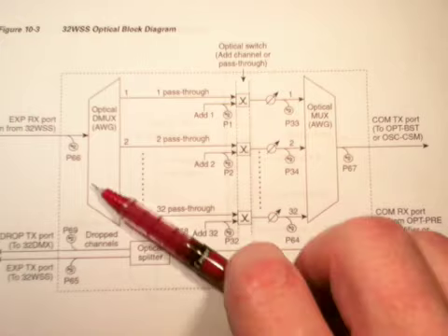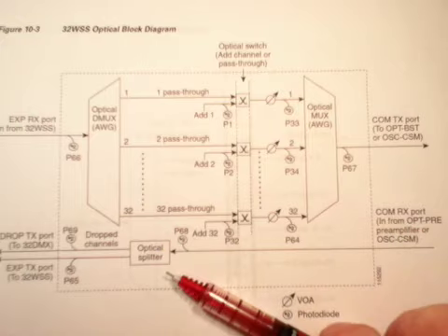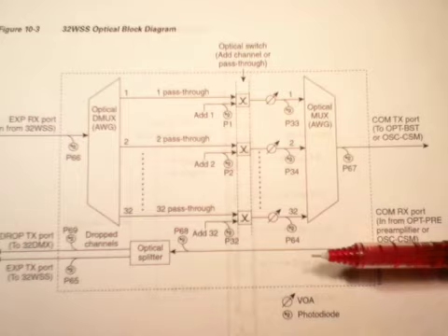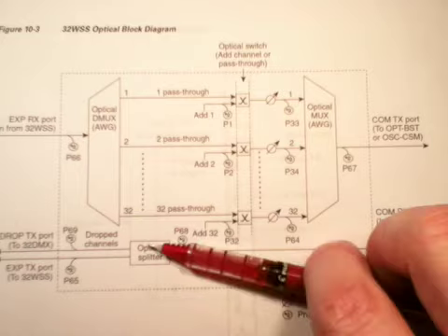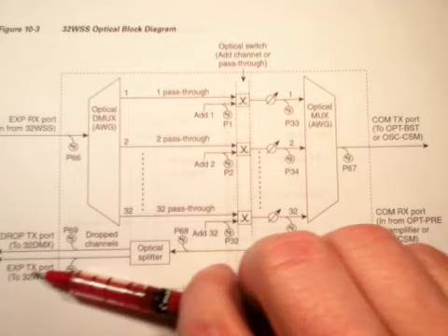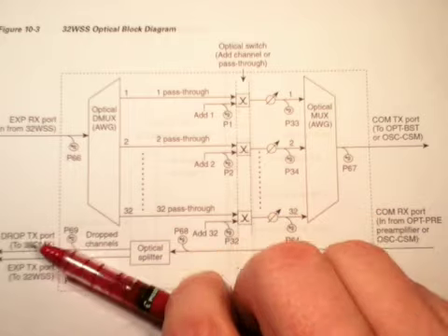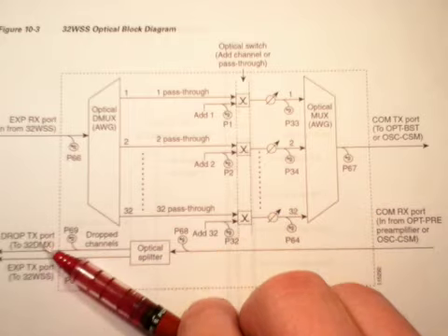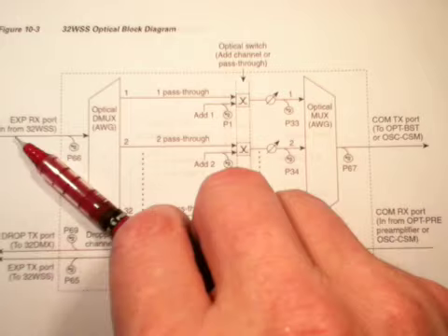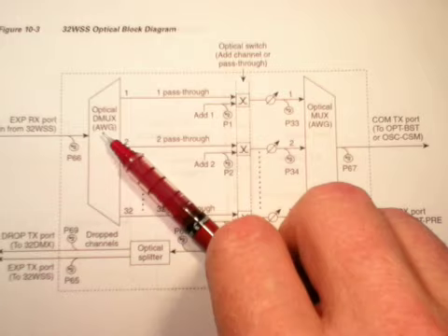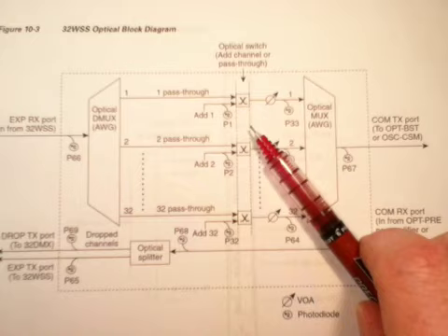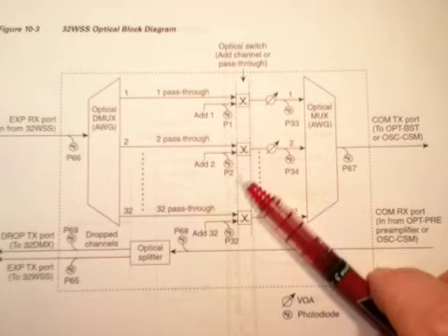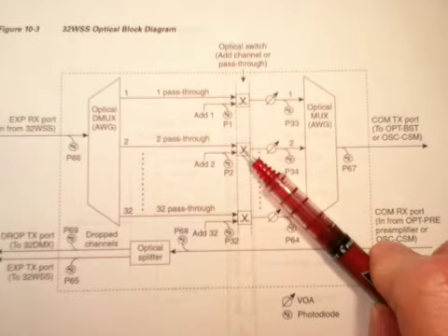And so the basic idea here is this is an add-drop multiplexer. On the input of this device you have an optical splitter which allows you to drop, sending the drop signal with all of the wavelengths onto a DMUX, and then you reroute that around to the input of the AWG, and here's where you can add. So you have to drop a channel before you can add a channel.